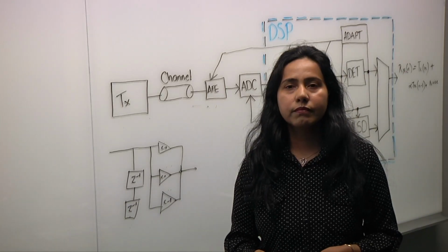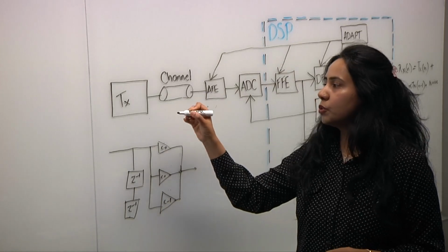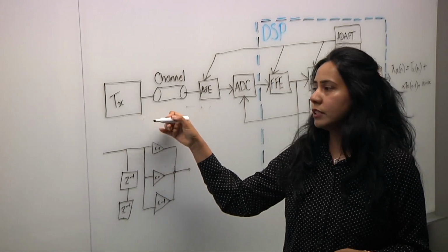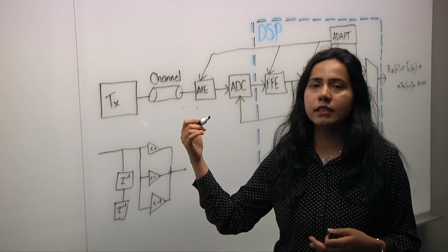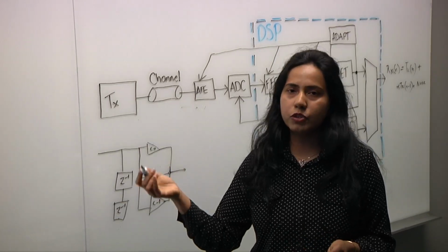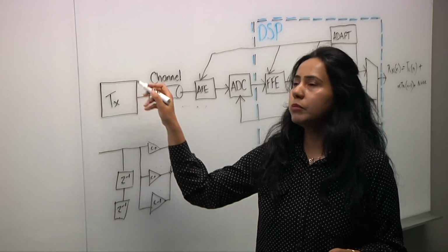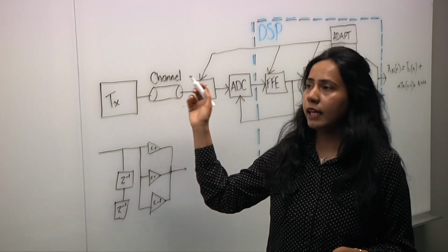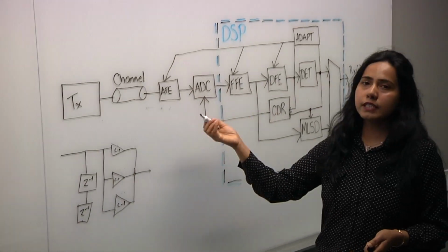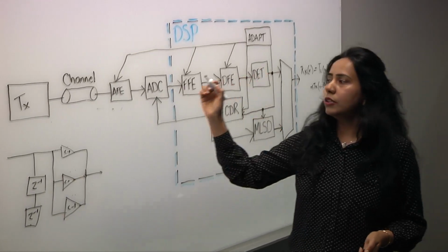And with DSP, you have some programmability built in there too, right? Yeah. So I was just mentioning the transmit side of it. The tap coefficients can be, for PAM4, a 4-tap filter, or you can have 5 taps, and you would be able to optimize that for a given channel. And of course, going to the receiver side, the DSP actually is in the receiver side of the link.